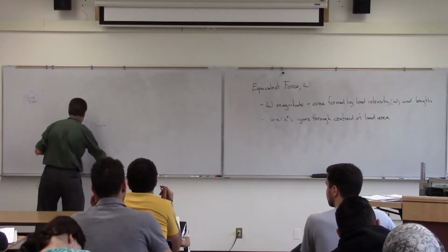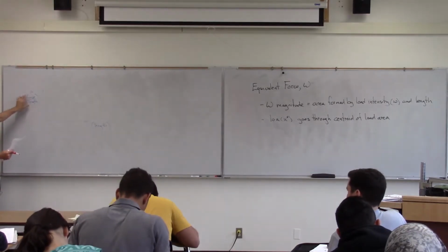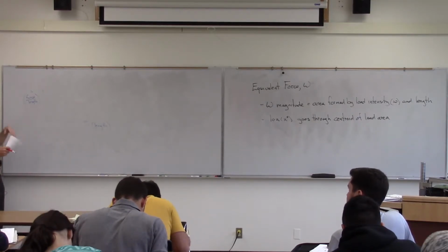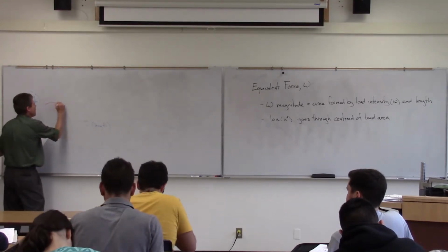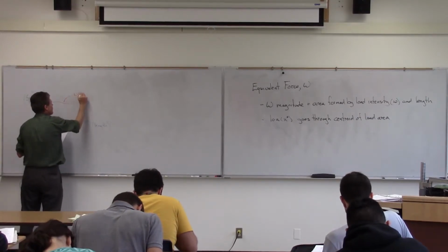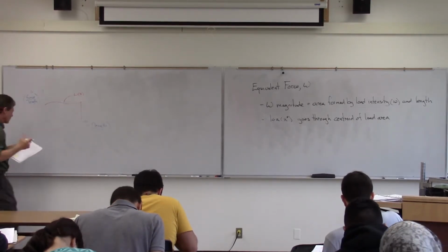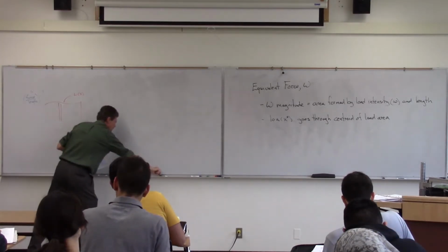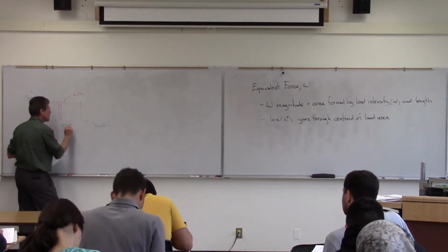Okay, so this force area is going to be described in terms of this small omega here, or small w, which is force per length. So it's going to be pounds per foot, pounds per inch, newtons per meter. And then oftentimes we'll be given that load in terms of a function of x. And all we're going to do is the same sort of thing. We're going to take our newfound ability to calculate and integrate.